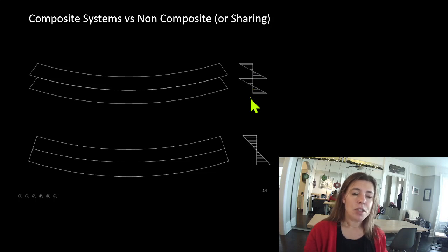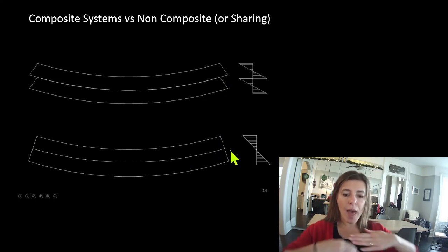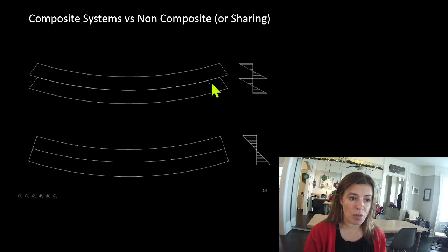that distance. Do you guys remember when we were calculating the shape property for bending? For a rectangle specifically, it was BD squared divided by 6. So the D, or the depth of the member, had a huge impact on it. So here we have two members that are the same depth. Here, we've glued this plane together, so that can't slip relative to each other. This slippage can't happen right here. This means we've made one beam that's much, much deeper.